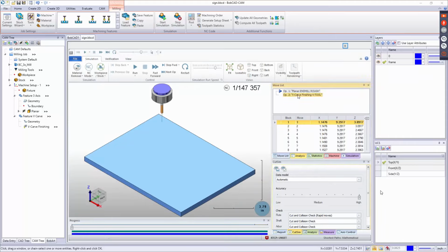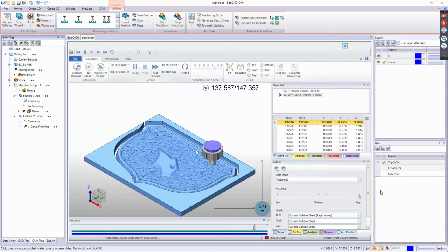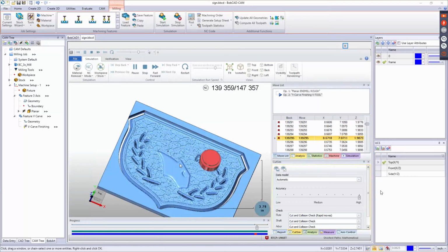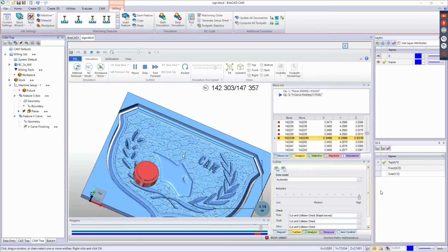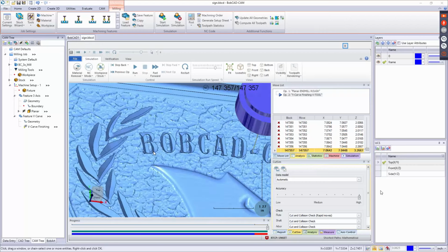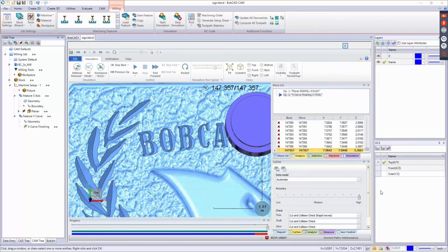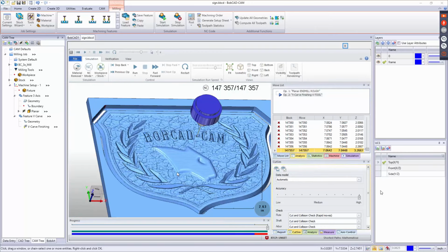And again, we'll skip that planer just to show the V-carve. So I may still get the result I'm looking for, but a little bit cleaner. Yeah, that looks a little better. So the size of your tool can really make a big difference when you're doing the V-carve in affecting the total depth that you're going to go. Yeah, I can go in with a larger V tool and it would do even less than that. And then lastly, I would just do a profile around the outside.